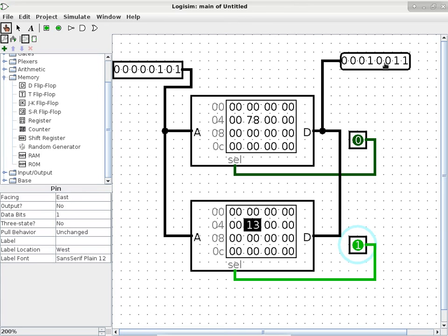Now this is greatly simplified compared to what you have in a computer, but in terms of principle, it is really the same. You have an address bus to tell the chips which location. You have a data bus so that the chip can tell you what is the content at the location. And you have a selection pin to say, okay, chip number blah, I want you to pay attention and everybody else shut up. Is that okay so far? Okay. So just to give you a quick analogy of how to combine multiple chips so that we have a larger logical memory space.